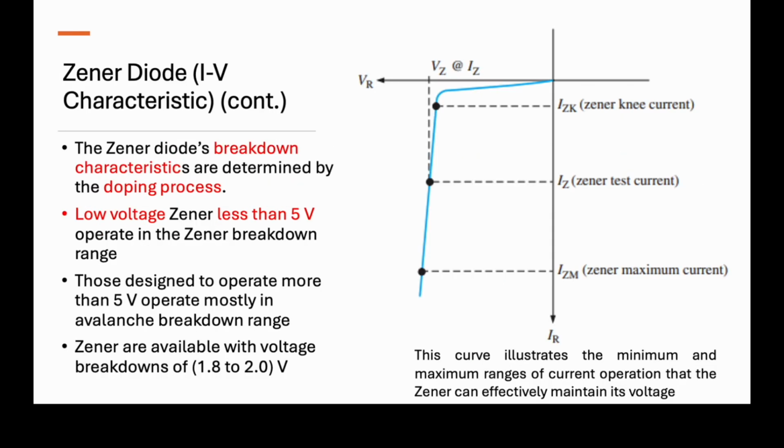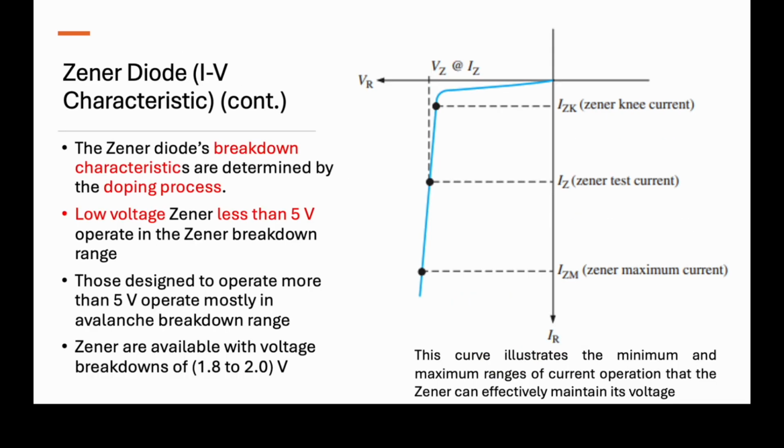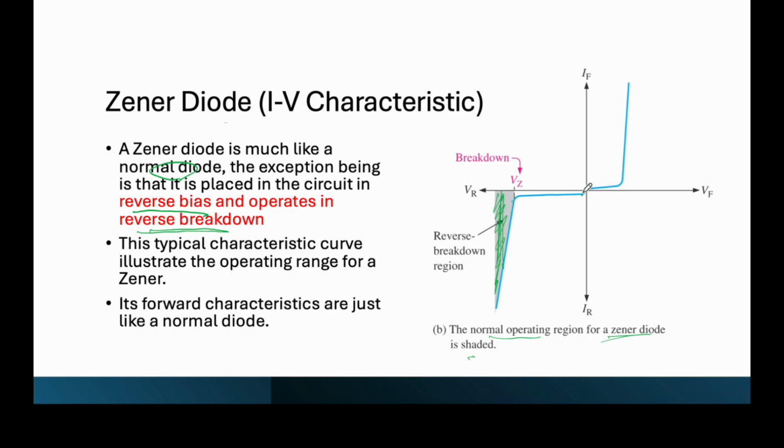For a Zener diode, let's look at this. At this particular region, at the VZ here. This is the VZ. VZ is the value of the breakdown voltage that makes the Zener diode start to turn on, start to work or operate. If you look at the graph here, before this VZ, the IV characteristic changes slowly at this particular part.